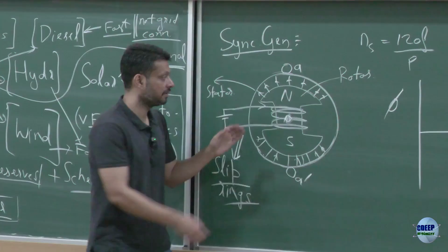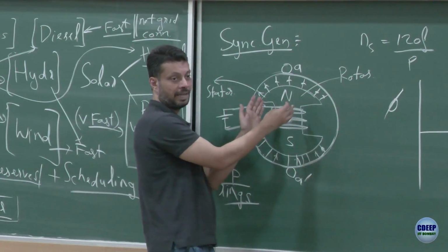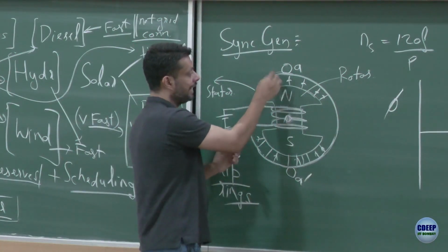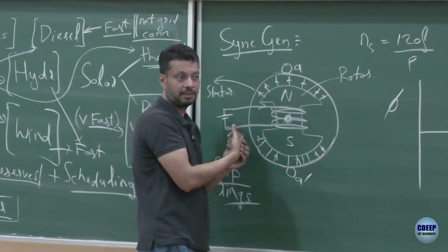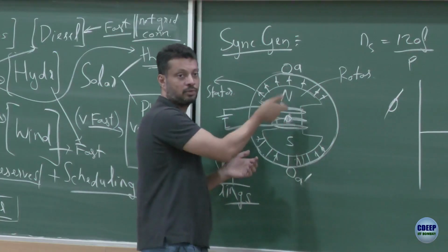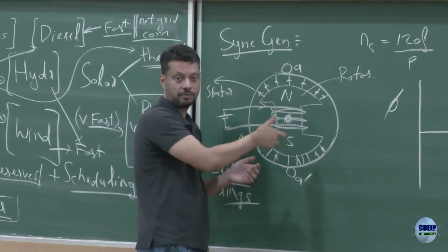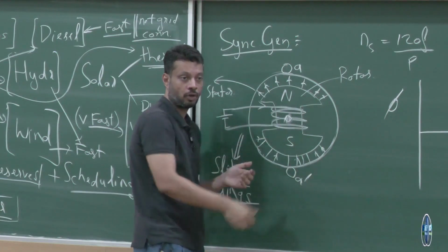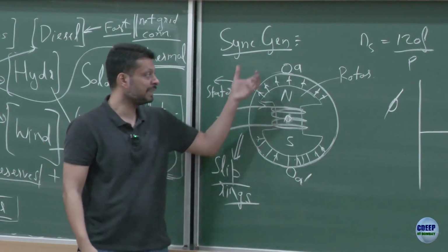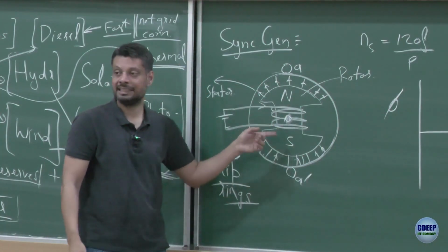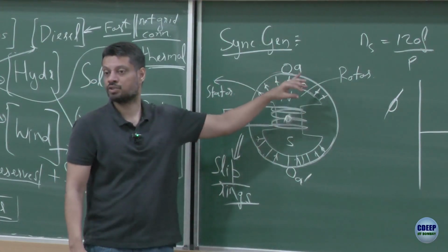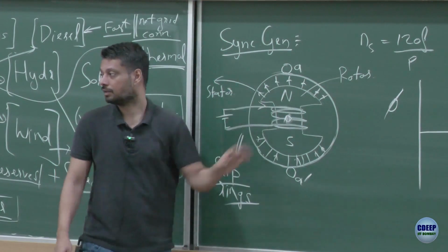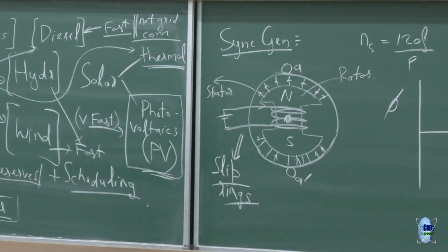So as of now it's 0, if I rotate it by 1 degree, you will have one line of flux linking. If you rotate it 2 degrees, two lines cutting from both sides. If you rotate it 3 degrees, 3 lines and so on. So the relationship between the flux linking and theta is linear because this is uniform flux. Is that part okay?